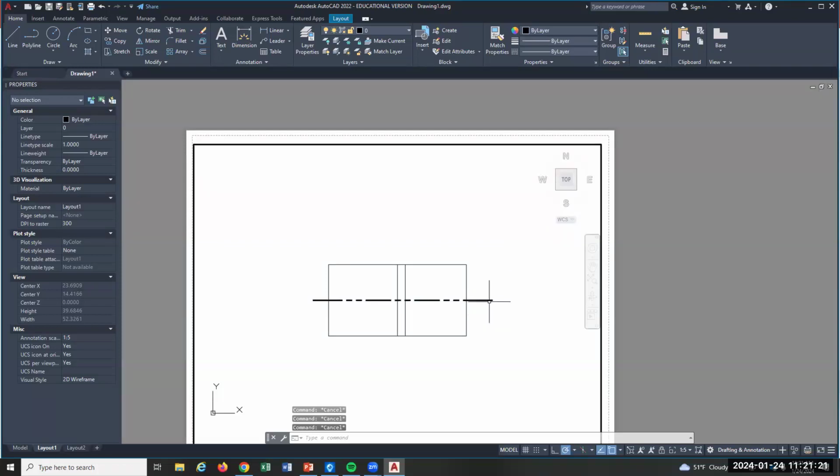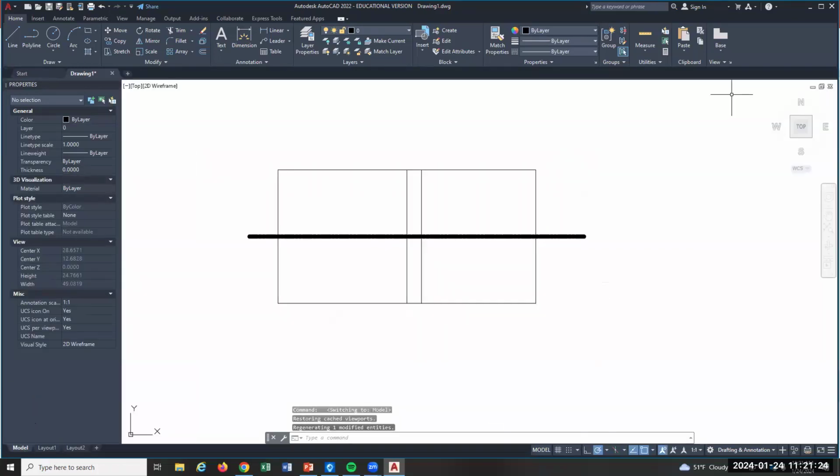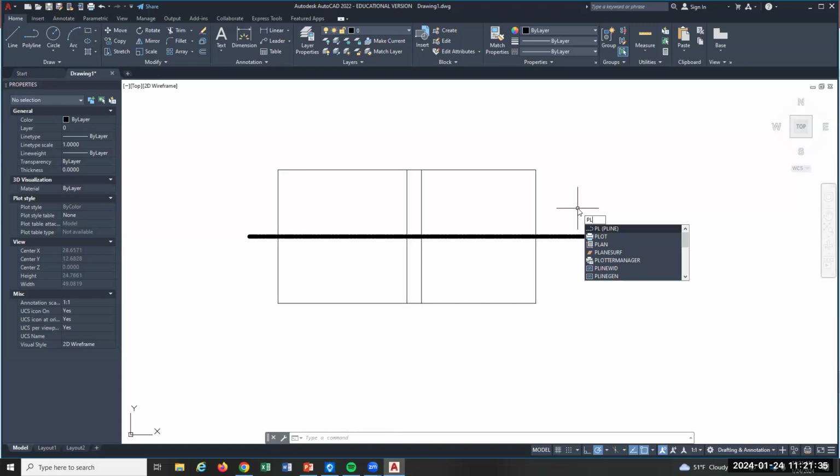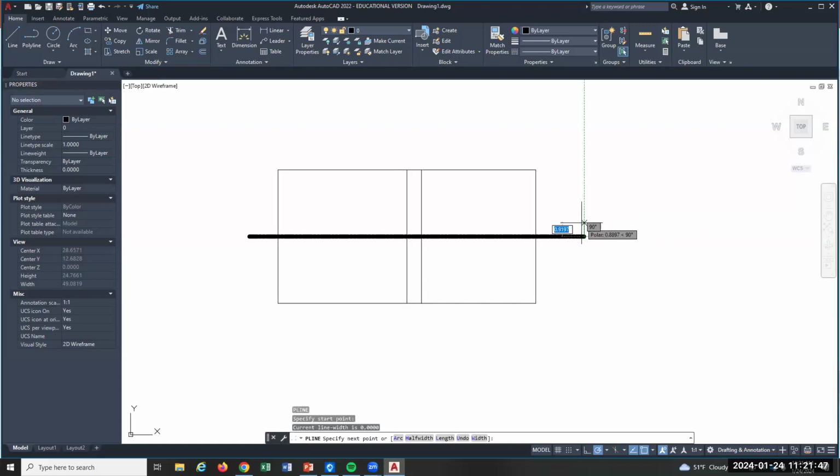The other thing is getting the arrows on. So there's a number of ways to do this, but I use P-line because these arrows are supposed to also be bigger than dimensioning arrows. Okay. So polyline allows you to add thickness to lines and also create arrows, so it's kind of nice. So I'll go polyline, I'll draw from, and you can see the options for polyline. This is kind of an advanced thing. We probably didn't even cover polyline in the first AutoCAD class. But you can add width to a polyline.